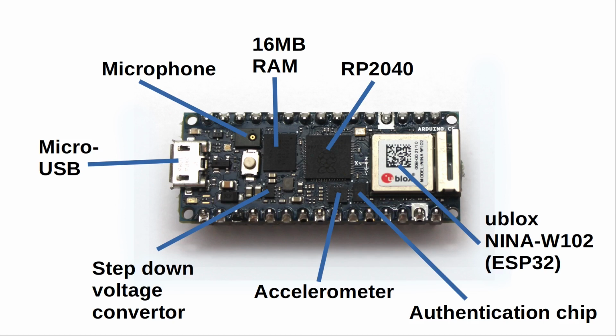This is different to MicroPython, which allows you to create a file system and store files in that memory. On the Raspberry Pi forums, there's talk of adding that functionality to the Raspberry Pi Pico, but at the moment you cannot transfer files to the flash memory except through your code. The files I was hoping to serve up include the HTML, JavaScript and CSS files.